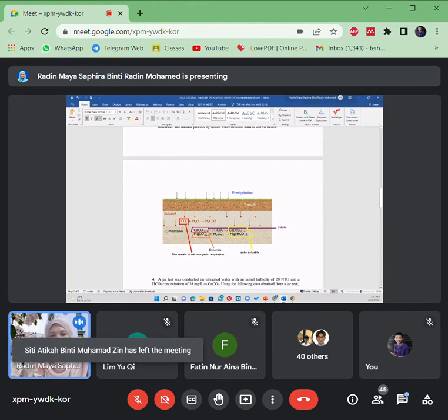So the process in the subsoil, there is carbon dioxide with water contributing to bicarbonate, right? The bicarbonate then reacts with the calcium and magnesium in the limestone. So that's why this produces the substance that makes the water hard. Okay, calcium bicarbonate or magnesium bicarbonate, which are soluble. Okay, if there is a lot, then what happens if the water hardness is high?